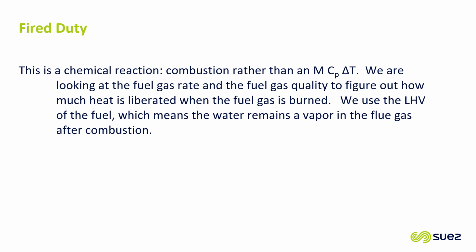There's two fuel gas heat values. Refinery would almost always use the LHV, which is the lower heat value, which assumes that all of the water vapor that's formed as a combustion product leaves as a vapor in the flue gas.